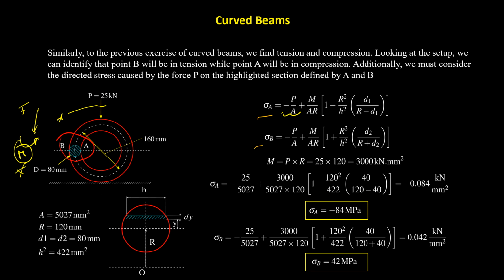And again, be careful of this. This doesn't have anything to do with the Winkler-Bach theory. It has to do with the fact that this force causes a stress in the sections of the whole ring that we're studying at the moment. But this part is how to calculate the stress caused by a moment in a curved beam. And well, this is it. This is the procedure to solve these types of problems. Thanks.